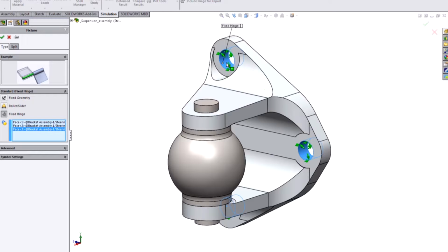So, for example, start off at the 3 hole locations. I'm going to assume they're basically pinned. We call it a fixed hinge relationship. The diagram shows a little graphic of what that means. Basically saying the hole location does not change, but it's free to twist locally around it if loading causes that to happen.